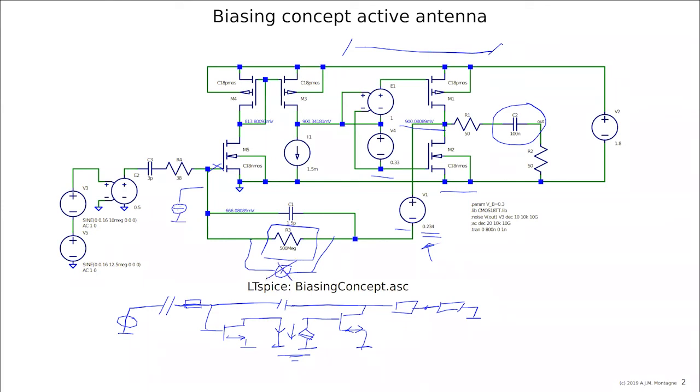And this one generates across the source impedance C3 a voltage, which means that the current noise causes a ramp up of the voltage noise for low frequencies, and not like 1 over f. 1 over f would be like this, but like just normal 1 over f squared for the spectrum in volts squared per hertz. And this point, of course, should be low enough. So this sets a noise requirement for this resistor.